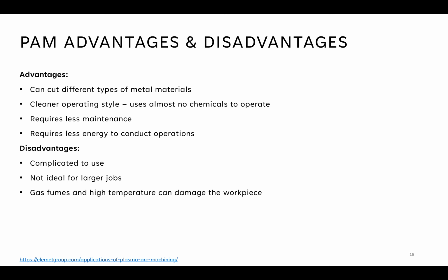Again, since it's melting based and not electron based. The disadvantages are that it's complicated to use. This is very common, as we've seen, for these types of specialized devices. And this is not ideal for larger jobs, just naturally due to bed space or just the volume of the enclosure, and also due to its comparatively slower speed. The gas fumes and high temperatures that are involved in this kind of machining can also be very damaging to the workpiece depending on the type of material used.